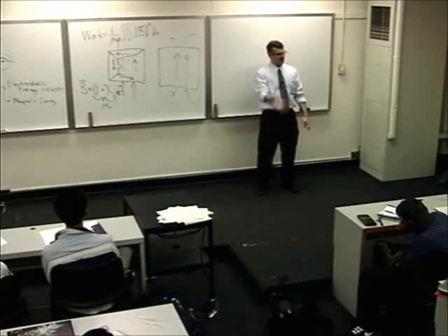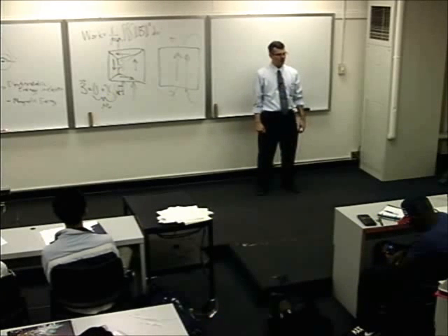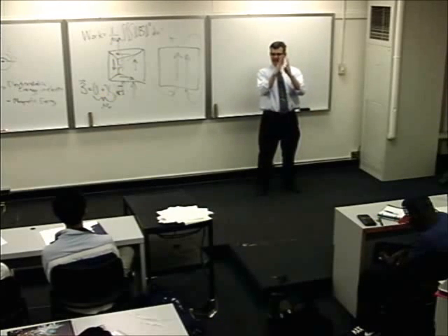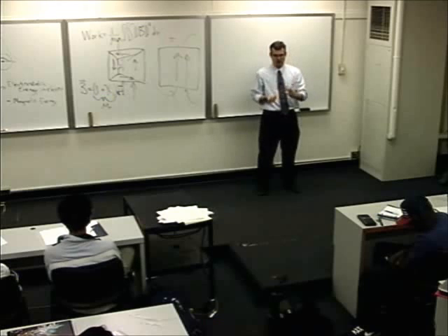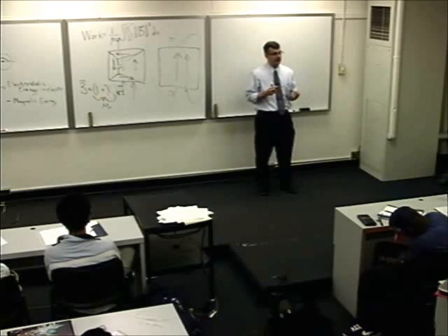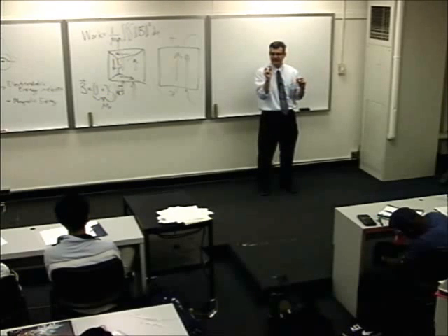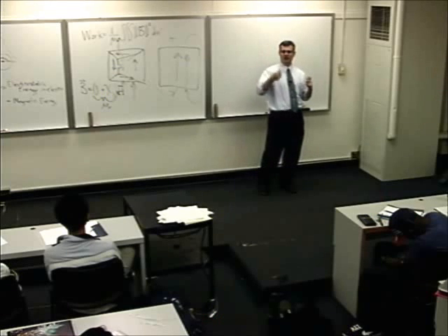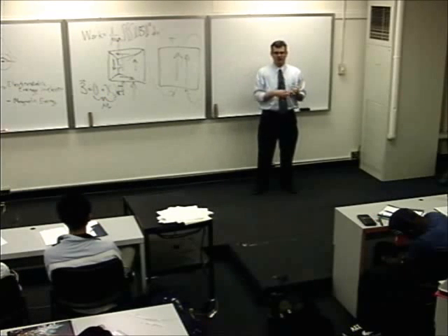Because remember, if I have an oscillating magnetic field in a material, I will also make ohmic losses. And so what you find in those types of materials, especially in the transformer core, is that they'll break up and laminate the iron. So you have a sheet of iron or a rod of iron, a little bit of insulating material around there, and then another rod and another rod. Another thing that you will also see is that the material could be made out of little iron particles that are individually ferromagnetic, but sprinkled into a plastic that insulates the particles from one another. So you can't get eddy currents set up in the material when you impress an oscillating field on them. But you can still get relatively high mu sub r.